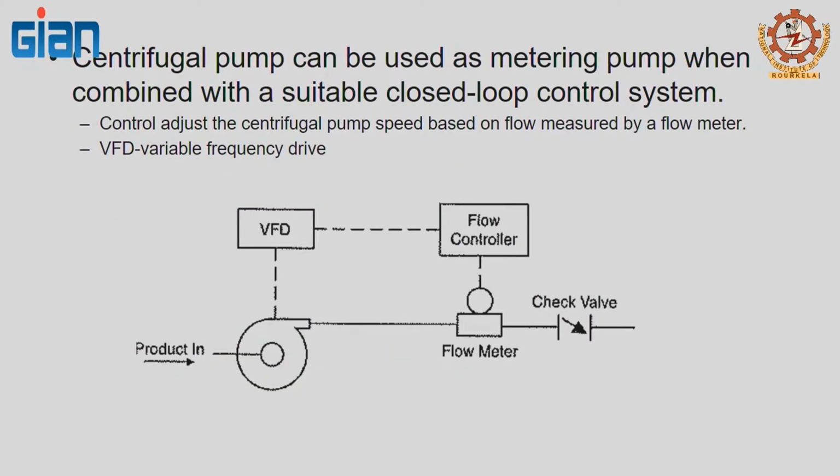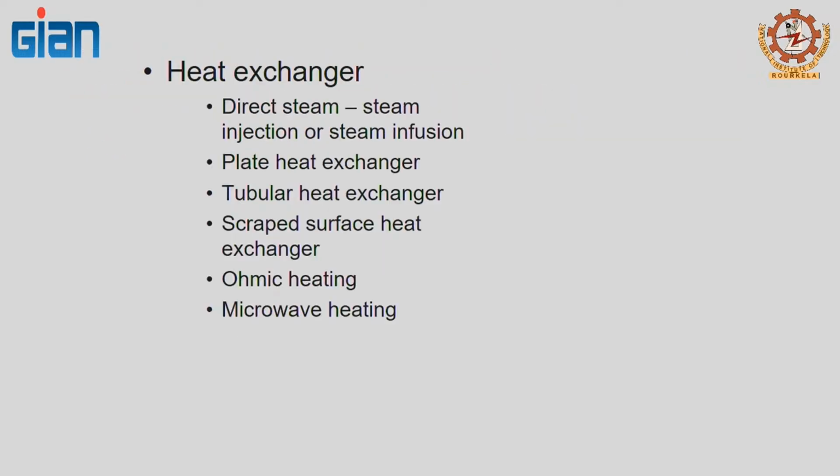You can use a centrifugal pump as a positive pump when you add what they call a VFD, variable frequency drive. This controls the variability within the pump and makes it consistent. So, instead of a 3 to 6 gallons per minute flow rate change, the VFD kind of modulates that and tries to consistently deliver a constant flow rate.